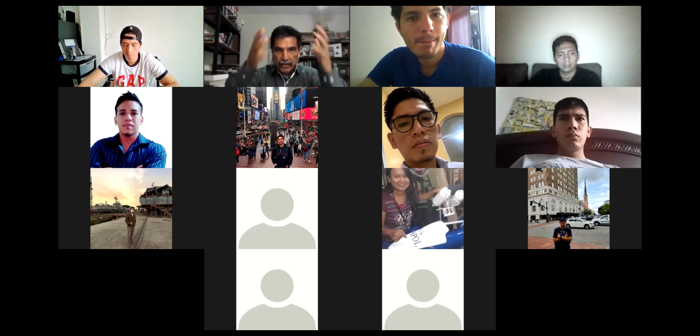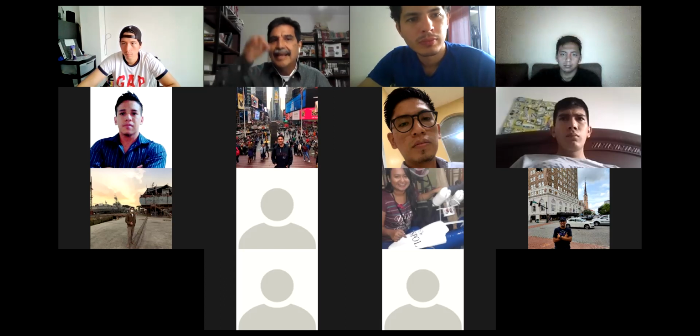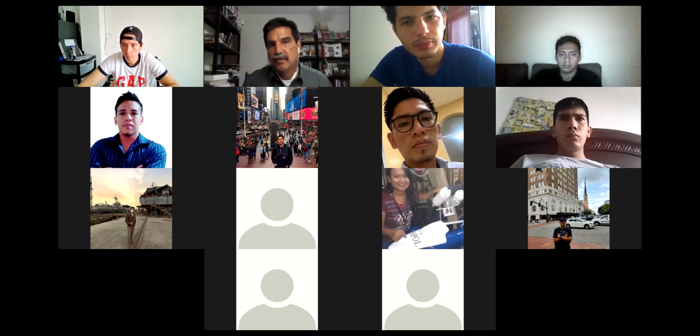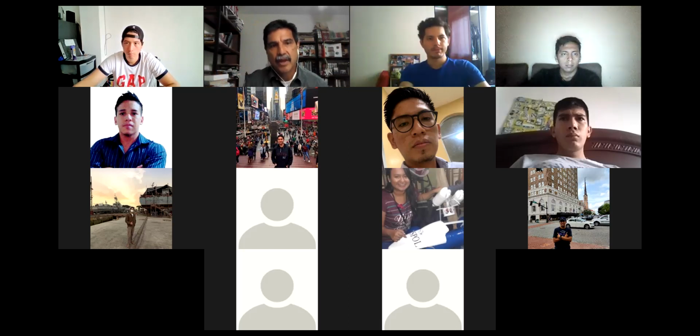So when you graduate and you need to do this analysis, what you need to do? You have to do this, then you have to do that. And in that case, yes, you have to consider exactly the amount of frames that you have in the ship. Take it from the plan, or go and measure. So you have the spacing between frames. The thickness, go and measure the thickness. What is the thickness? It's not 8, it's not 9, it's 10. Okay, put it 10. But you know how to do it. Okay, so invent it. That's it.